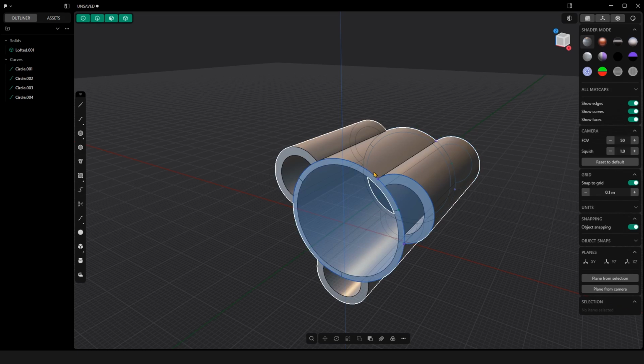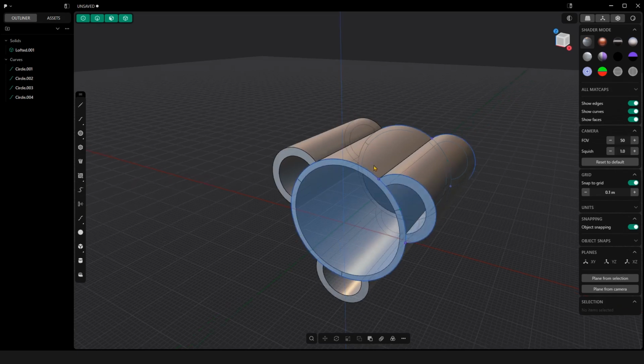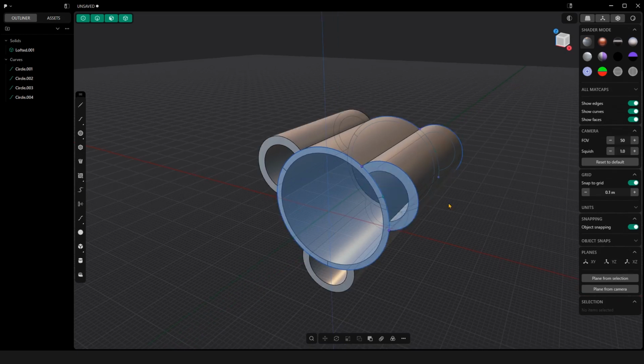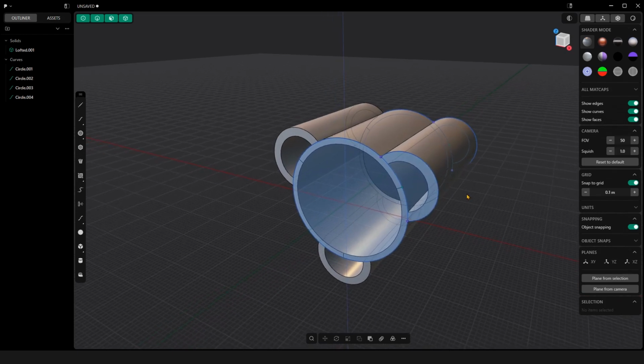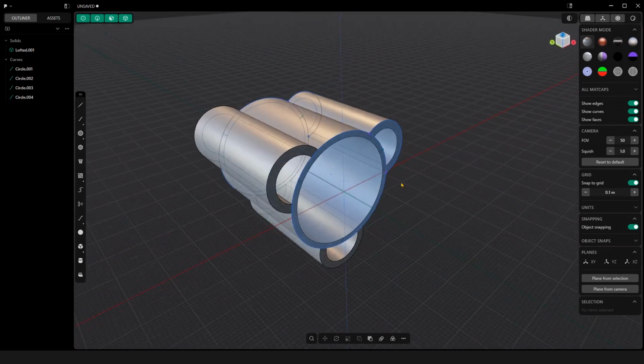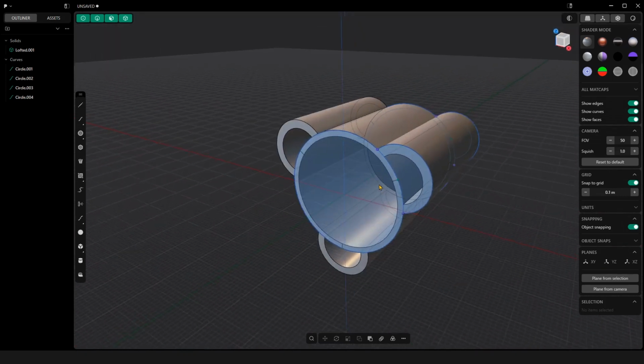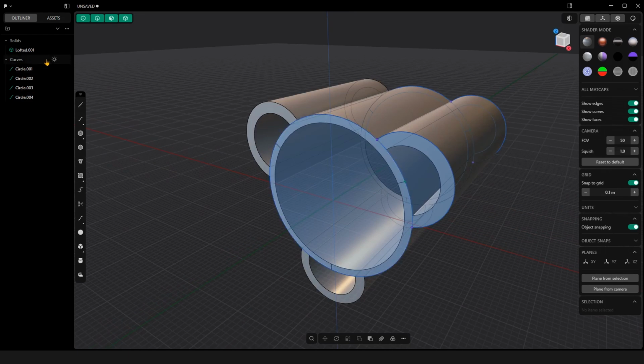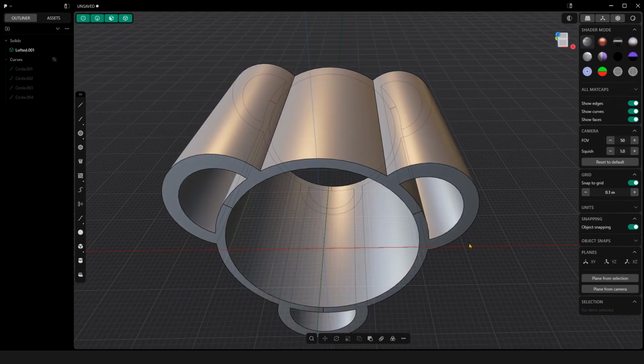So it's always a good idea to preserve the curves that you had drawn out, because at some point you probably will want to iterate and go back to those and rebuild your solids again from that, right? But for now, I'm going to hide them. There is this sunshine icon here. I'm going to hide it.